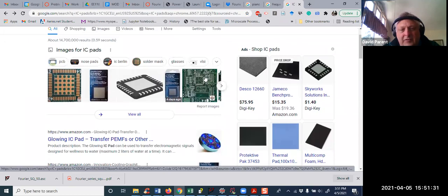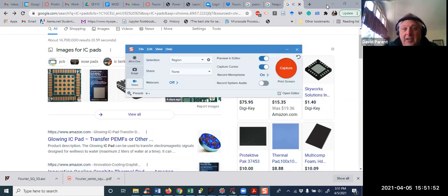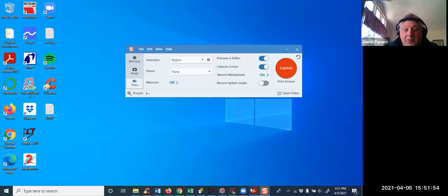So these wires here are the external part of the chip. Then when you open it up, you see these little pads here, and there's wires that come down to it. And then it connects to the actual piece of silicon, right? So these wires, right? Wires we're always saying is 0 ohms and 0 everything, in fact, have resistance, inductance, and capacitance.